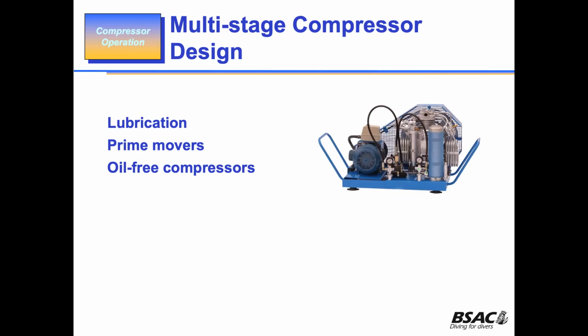Because what happens when you get oil and oxygen together? Fire. You could get a few other things as well, believe it or not, but you're right. Oil and oxygen together become very combustible, and you've got heat there as well in the compression cycle. So oil-free compressors are for if you're going to be compressing high mixes of oxygen and nitrogen, i.e. nitrox.